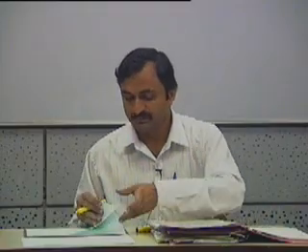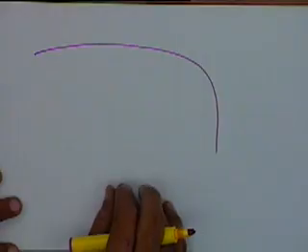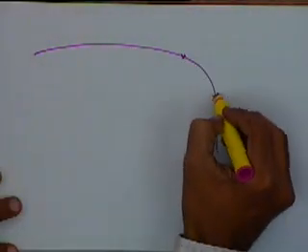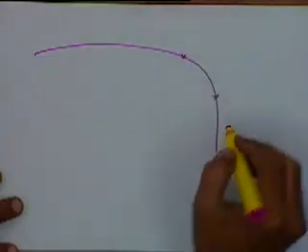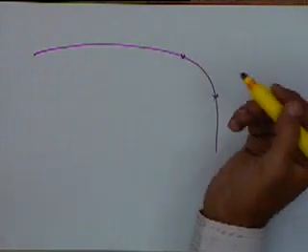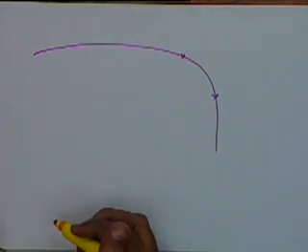See, it basically depends on the application whether you want to have continuity or you don't want to have continuity. Okay. For example, right now I'm modeling curves, and if I say I want to model, let's say this is the front of my car. Purely from an aesthetics point of view, I might say okay, this is one curve, this is second curve, this is third curve, and I want to have C1 continuity purely from an aesthetics point of view. Okay. For some other application, I might not need this continuity, then I won't bother. Only when I need this continuity will I go for a formulation like this.